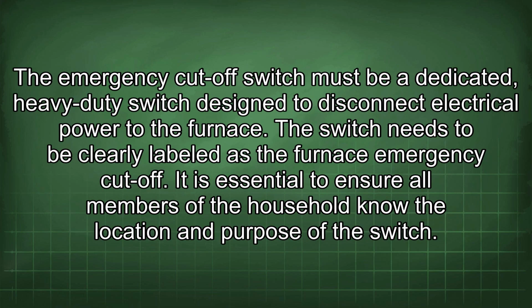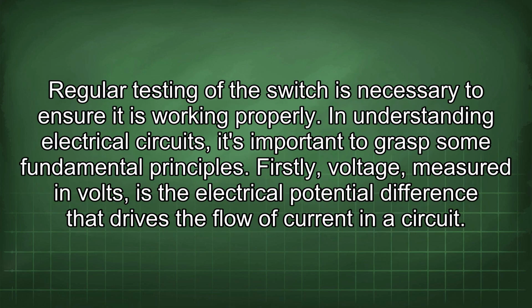The emergency cut-off switch must be a dedicated, heavy-duty switch designed to disconnect electrical power to the furnace. The switch needs to be clearly labeled as the furnace emergency cut-off. It is essential to ensure all members of the household know the location and purpose of the switch. Regular testing of the switch is necessary to ensure it is working properly.